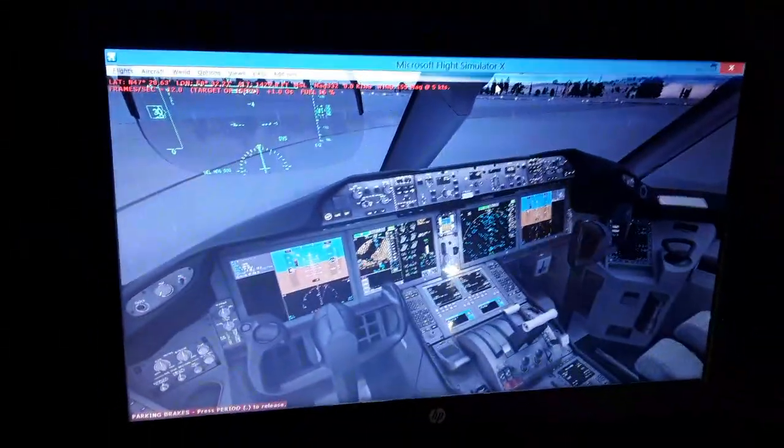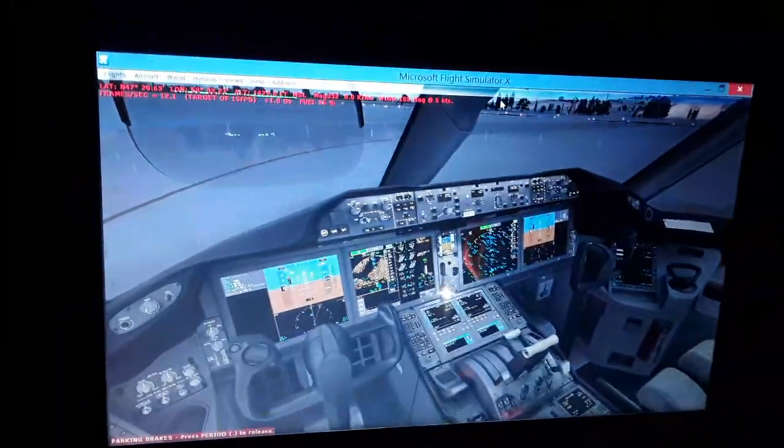As it flies, it burns fuel, so the center of gravity is shifted. Also, it's gonna calculate the loads from the passengers and the cargo. It's gonna give us the center of gravity for takeoff. And then the mean aerodynamic chord position of the forward wings is 23% with respect to the center of gravity. It's gonna give us the position with the maximum aerodynamic lift produced in the forward wings. It is also the position where the stall will begin in the top surface of the wings. The airflow will become detached, so we need to monitor over here.